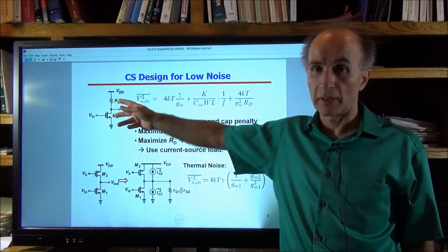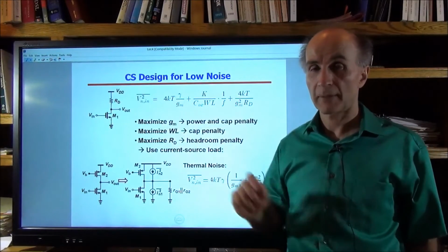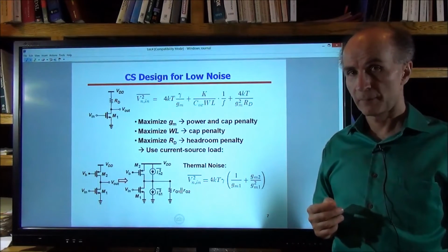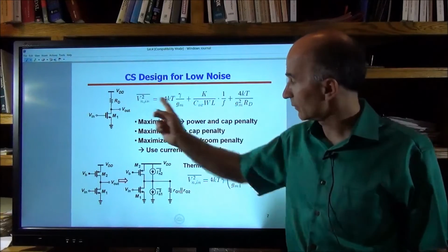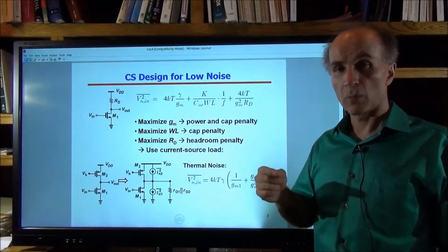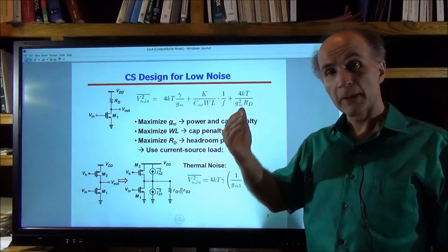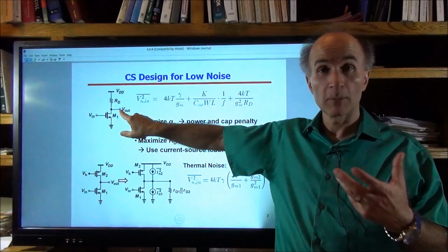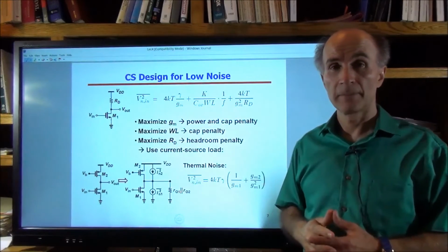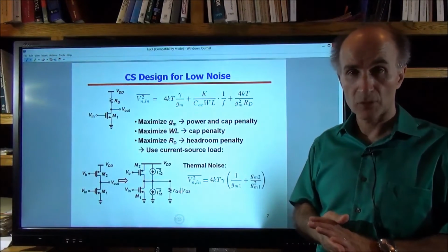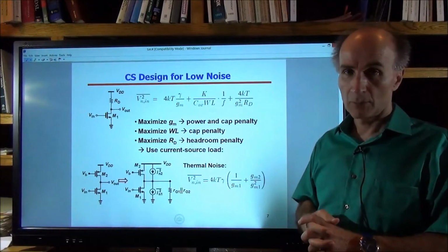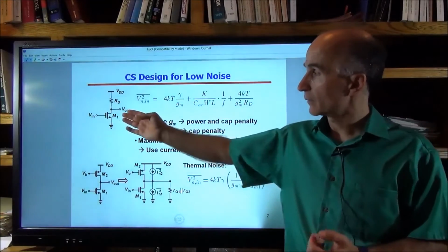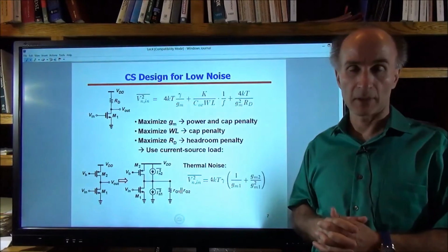We just have Ohm's law. Rd times Id is the voltage that we have here. So that voltage has to be accommodated by the supply voltage. So we say that as Rd increases to reduce this noise, either the supply voltage has to go up, or we have to lose voltage headroom, meaning headroom available for voltage swings at this node. Neither of these are desirable. So that's a trade-off that we face between reducing the noise contribution of Rd and reducing the headroom or increasing the supply voltage.